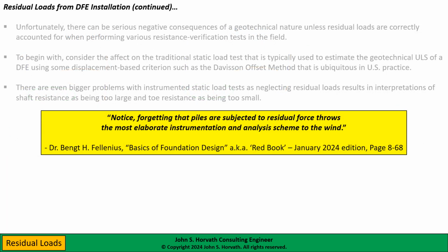And Fellenius noted this point with this quote here, which I take from his most recent edition of what he calls the Red Book, which he came out with earlier this year. Basically saying that if you have an instrumented static load test and don't correct for residual loads, you've wasted your time and you've wasted your client's money in the process, because everything you interpret is going to be wrong, rather significantly in some cases.